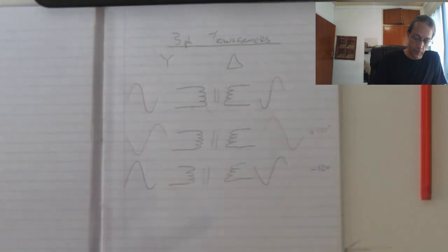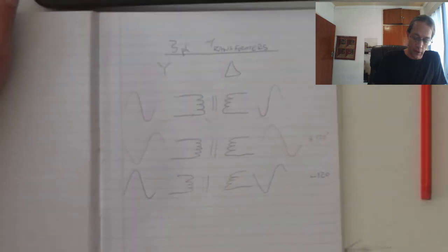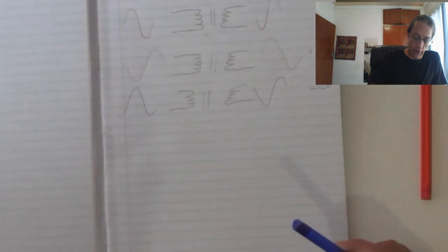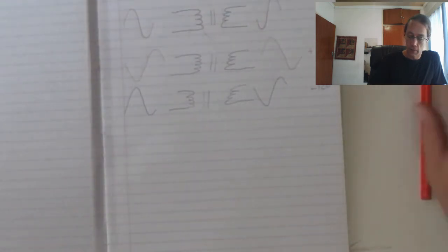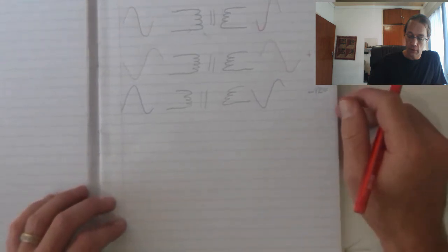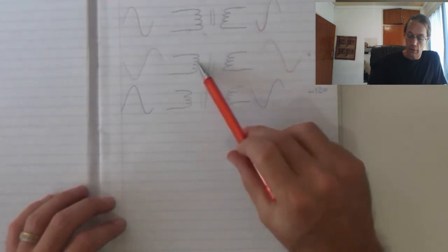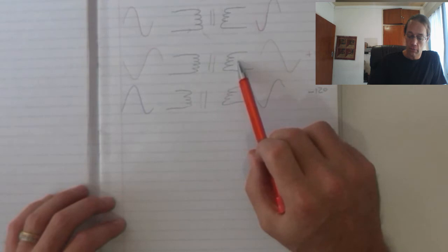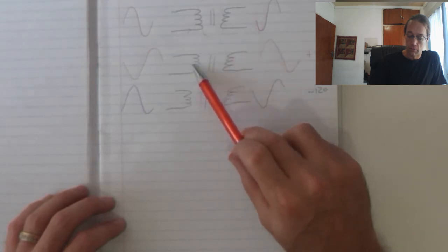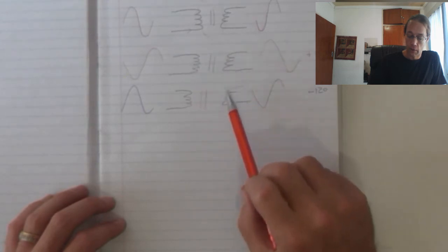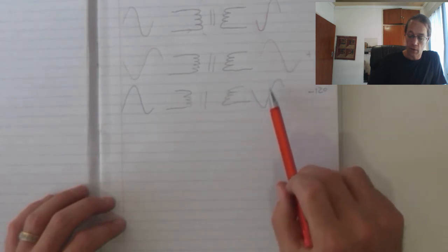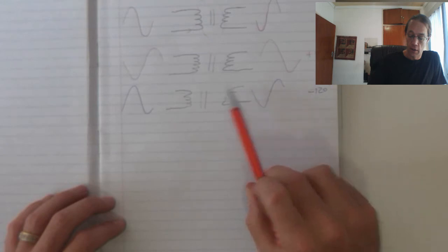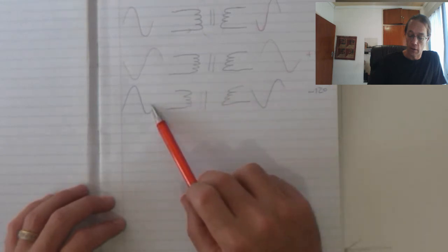All three transformers work exactly the same. The only difference between these three is when their sine waves actually start due to the phase shift of the signal. Each coil will influence the other one with respect to current and voltage that's flowing, and each one will then develop its 180 degree phase shift with reference to that phase's primary.